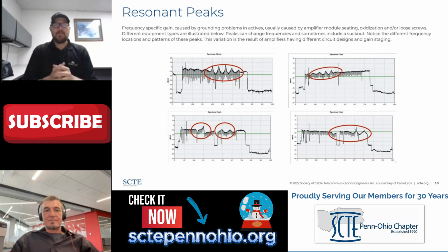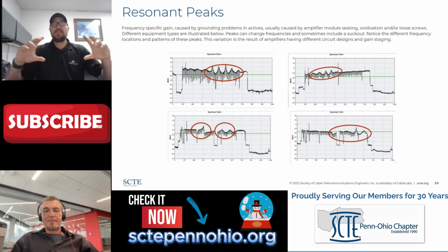But over years, through normal wear and tear and environmentals, some of the gaskets on the housing may deteriorate, water may migrate and get corrosion inside of the housing, particularly the RFI or the shielding gaskets that's in the housing, or the module retainer screws may loosen over time because of vibration and wind whip and things like that. And so the housings themselves can actually warp or twist.